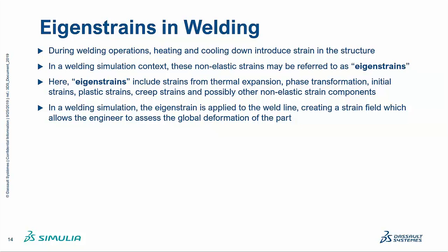In a welding simulation, if you're using the concept of the eigenstrain, then the eigenstrain itself will be applied to the weld line, creating a strain field, which allows the engineer to assess the global deformation of the part. That's the idea.